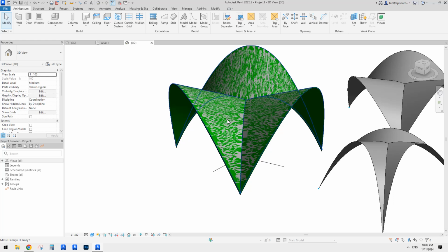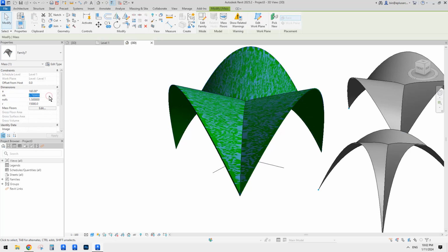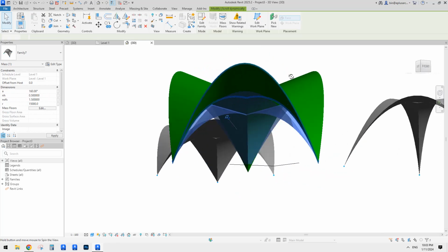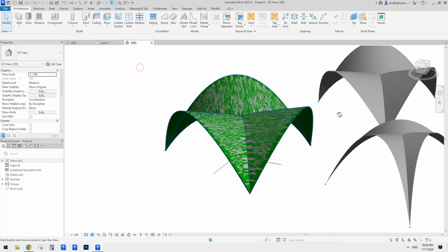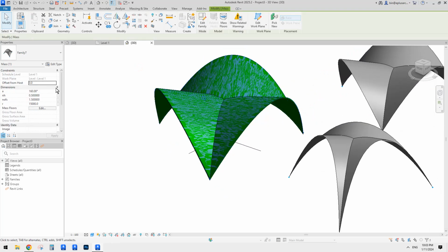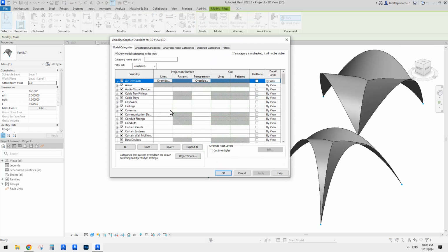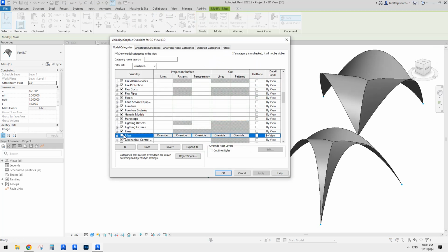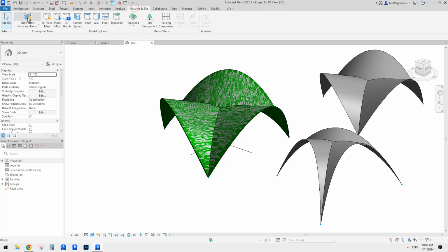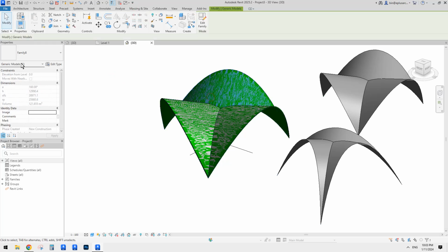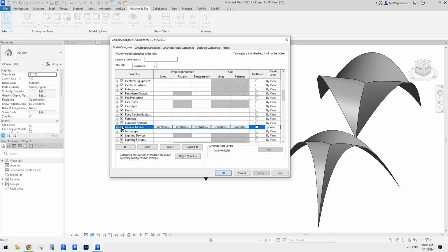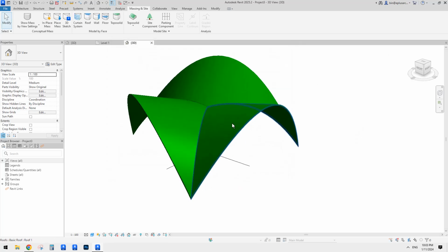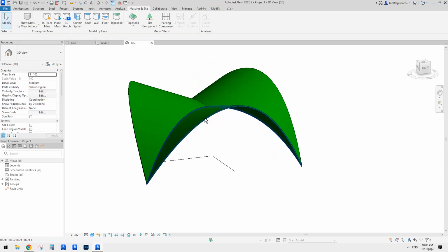And also you can change this one. So maybe I want to make it lower, and okay, so let's just select the roof and update, right? So now you can either hide them or just go VV and turn off the masking. Okay, so it's here, turn off the mask. Oh, not mask. Oh, it's a generic model. Sorry. Yeah, you can just go VV, go to generic model, turn it off. So it's all hidden, and you still have this